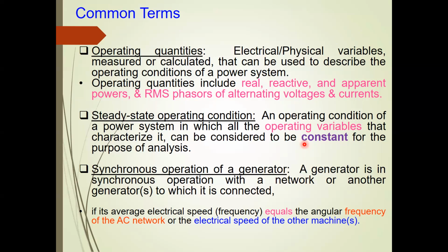But if the demand is exactly 500 MVA and generation 500 MVA, in that case, you will observe that the system frequency will be exactly 50 hertz, right? And then again, the bus voltage, let's say the bus voltage in the network is 132 kV, and let's say you have a 4 bus network or 10 bus network. All these 10 buses will have exactly 132 kV maintained.